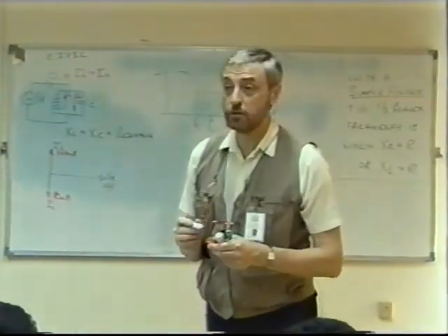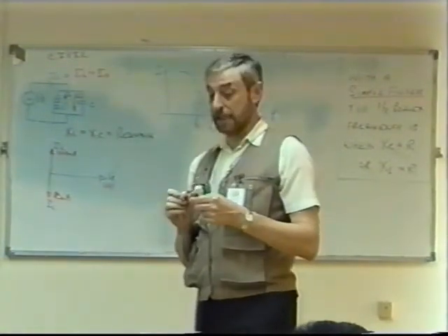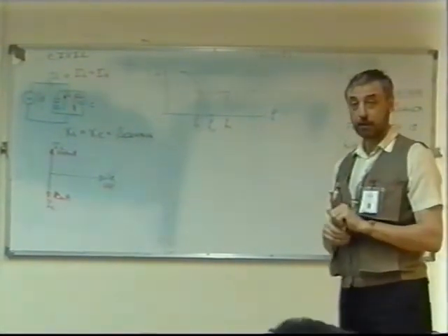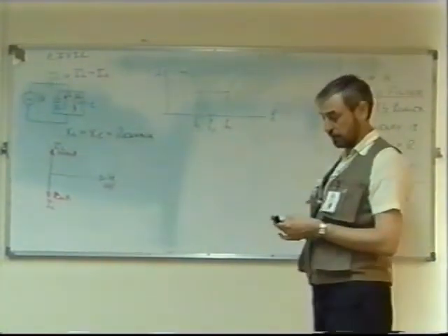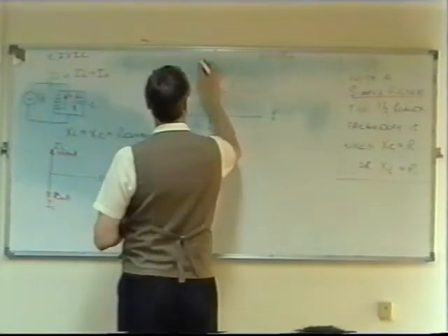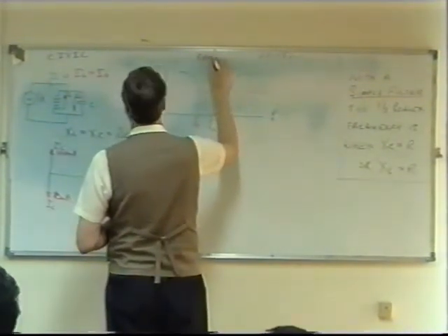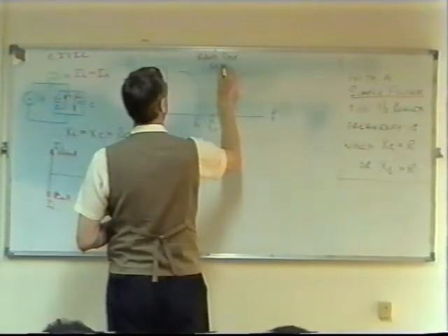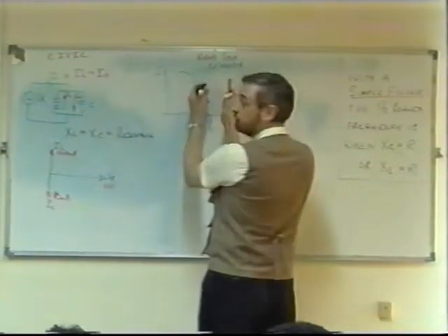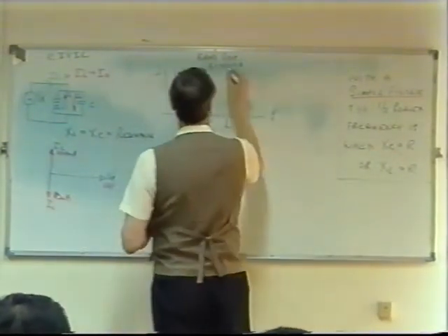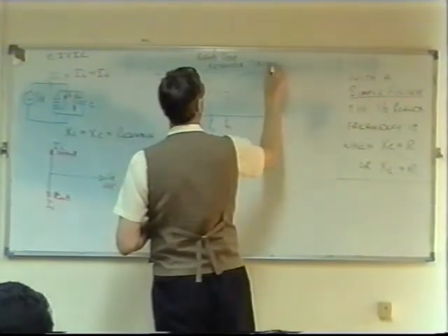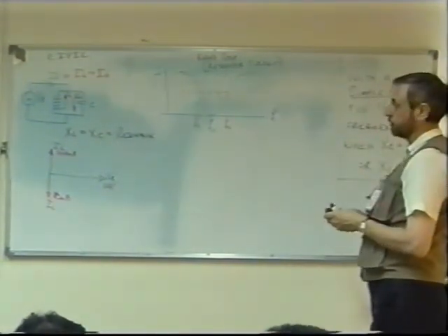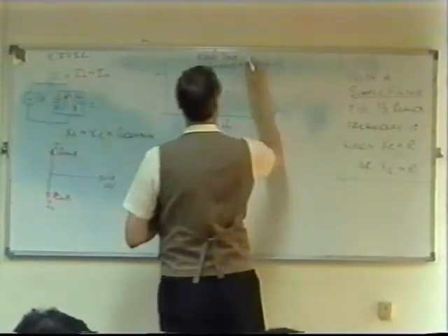Now, you used a word, what word did you use? Yes, it's a rejector, isn't it? Remember the other one was a band pass filter. This is a band rejector, like a band stop or a rejector. So there are two or three names that can be used for the same thing. You can call it a band stop filter, or sometimes the word rejector is used, because it's rejecting a band of frequencies. So sometimes we call it a rejector circuit, a band stop or rejector circuit. Or band stop filter, yes, I should really put that in.